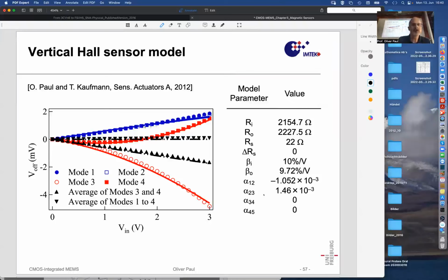The through curves are the model curves, the dots are the measurements, and I think we have caught the essence of what the measurement says. And it shows actually that if the betas are zero, if there is no junction field effect, then those parabolic responses are gone. The response will be like the black curve, black instead of red. And the black will be just opposite to the blue.